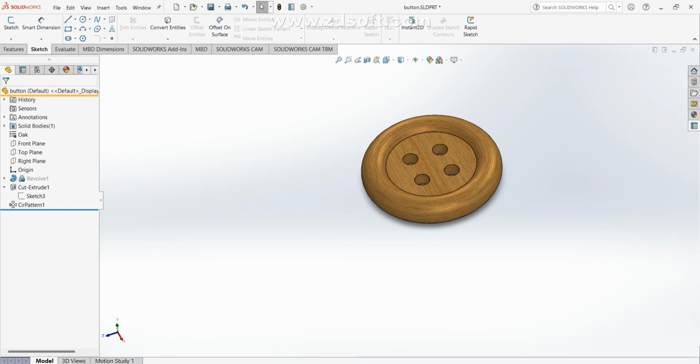Sorry, I put it in its right place, and everything is okay. The feature manager allows for a couple of different types of folders. One type enables you to group features together, which is especially useful when you have a long design tree and you want to put all the fillets together into one folder, or in assemblies when you want to group certain types of parts together. For creating folders, you just need to hold the Control key and select parts, assemblies, or